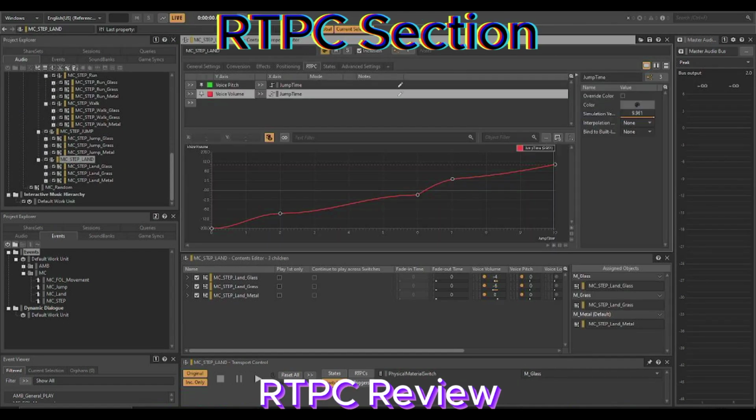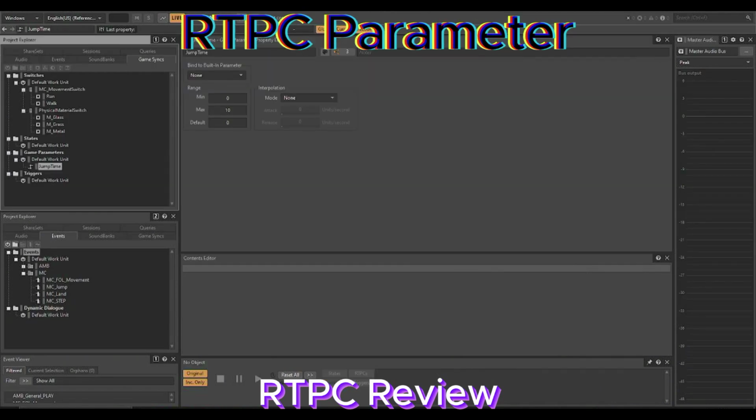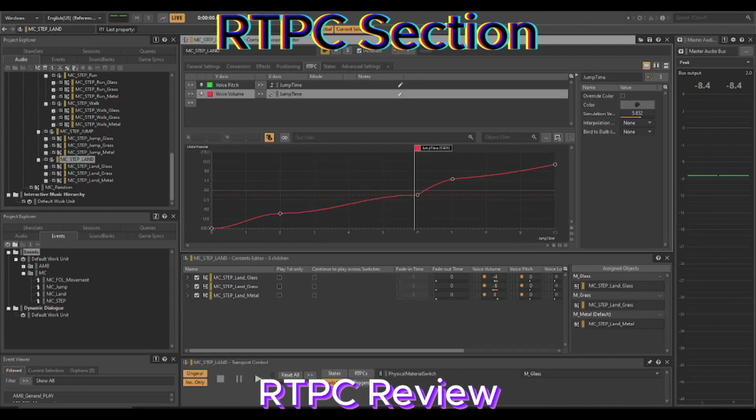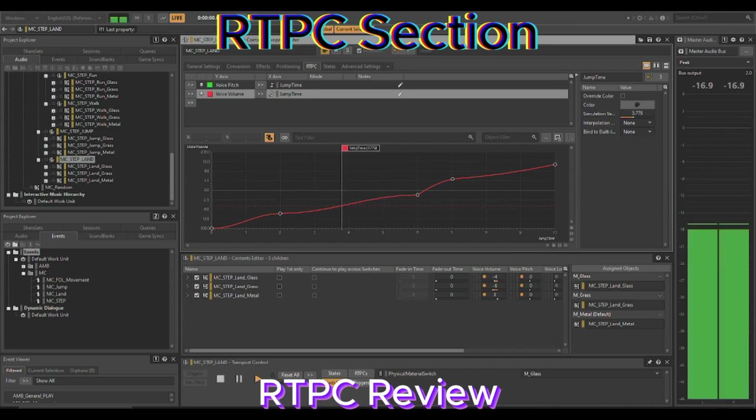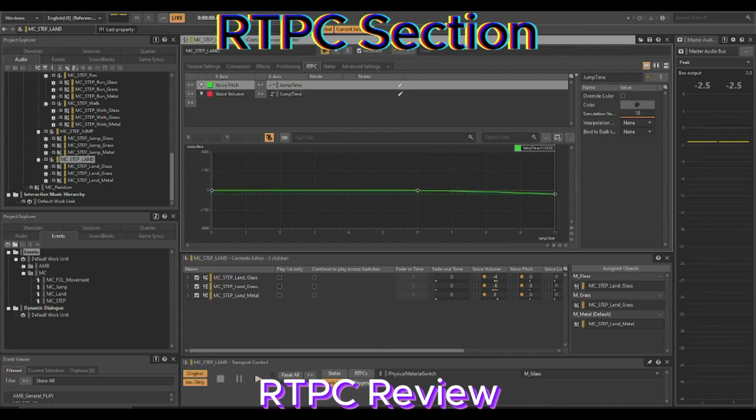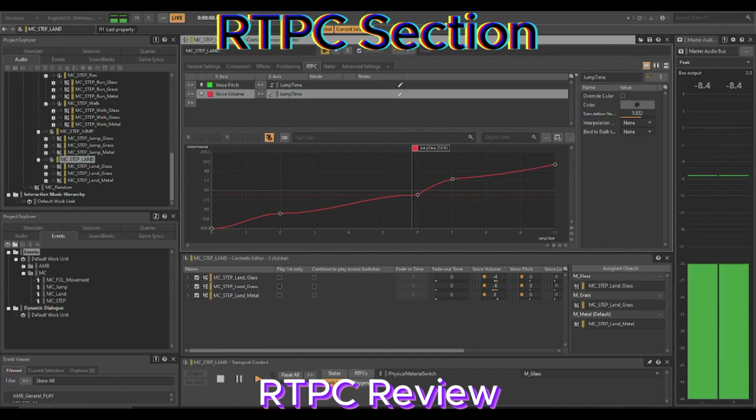I decided to add a little feature as I wasn't quite convinced about my landing feeling. It sounded same no matter how high I was jumping, so I created an RTPC which will evolve depending on the time spent in the air. In Unreal I managed to calculate the scale 0 to 10 thanks to a print, and it corresponding to 1 second. I drive the volume of the landing with this RTPC and added a soft low pass filter for the highest jump to bring a heavy feeling while landing.